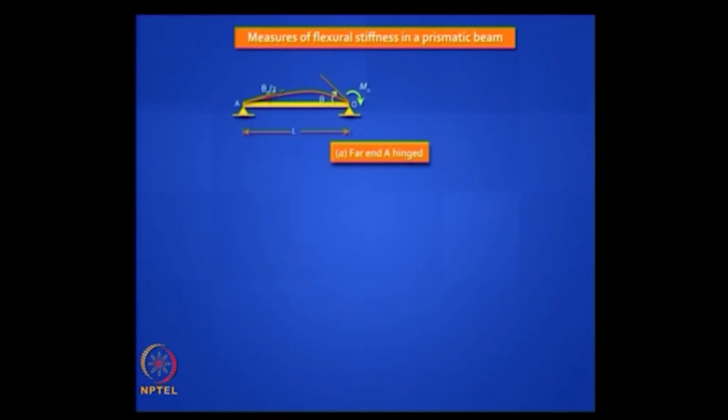So in this we will first, before getting into solving problems the hard way, get a broad introduction to displacement methods. We should understand the meaning of stiffnesses. Take this example of a simply supported beam subject to an end moment m0. You have a clockwise rotation at O and an anti-clockwise rotation at A. You can get a relationship between m0 and theta, right?